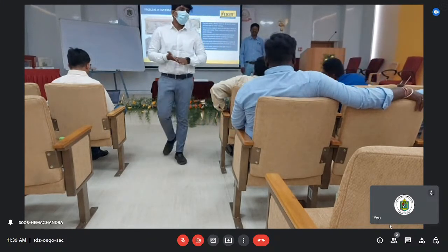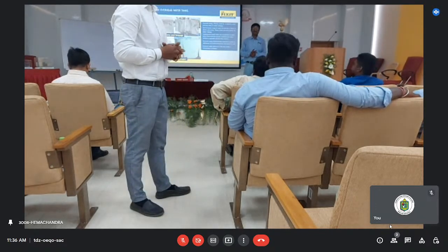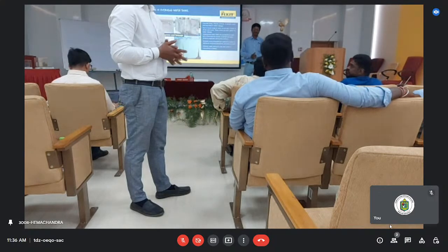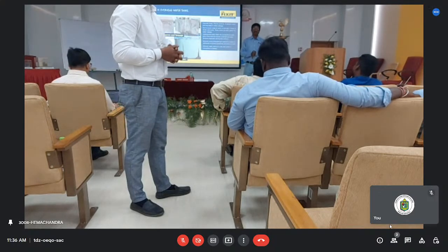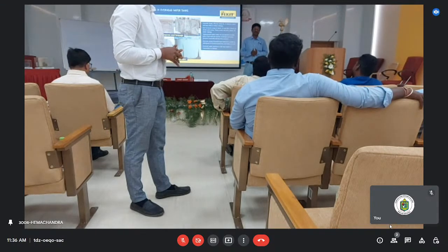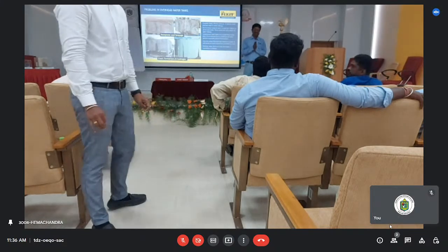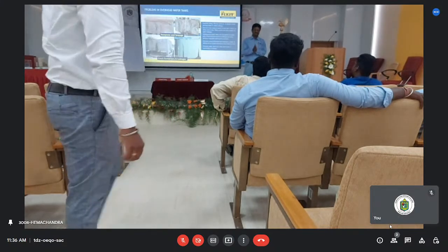See, my UGT height will be around 10 feet. I can't construct in a single shot in 10 feet height. I will do it in every 1.5 meters. So then in that case, whether I can cast the second lift as it is or you have to make some waterproofing because the joint will be there. What is the precaution I have to take for this?